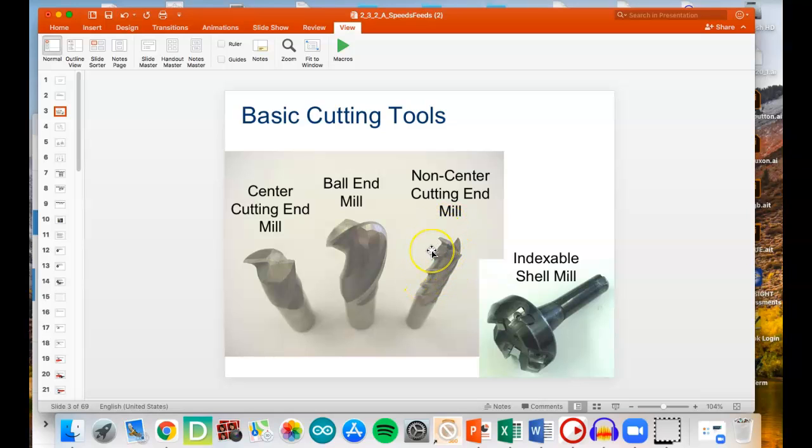So take the DR, kick that out, insert an M, and you've got a mill. What a mill does is it cuts on the side, and these razor sharp edges are called flutes. They come down, cut through your material and chuck it into the air. This one's center cutting, which means it can drill down into a piece of material similar to a normal drill bit. And this one is non-center cutting, so it's got a little pit right there, and it's really good for going around the outsides or insides, but not so much for going straight down into material.